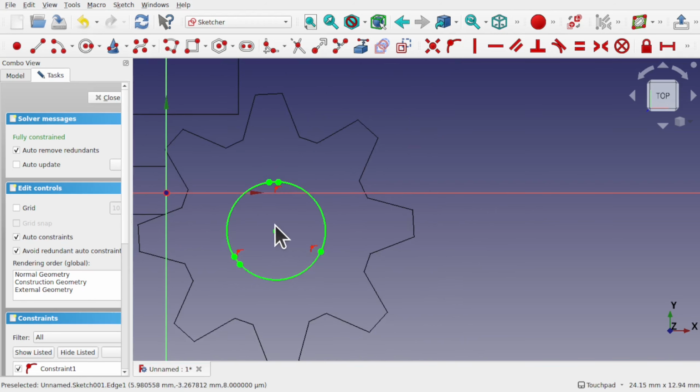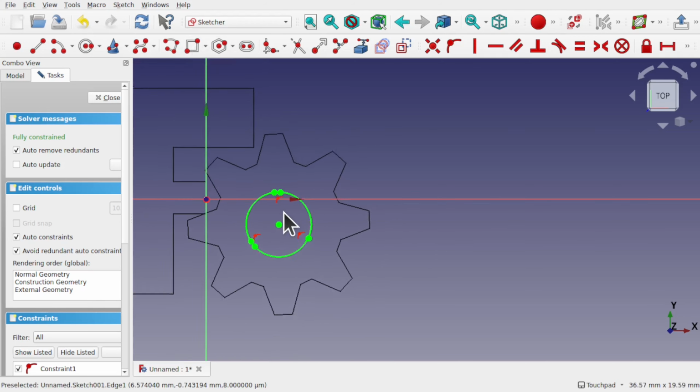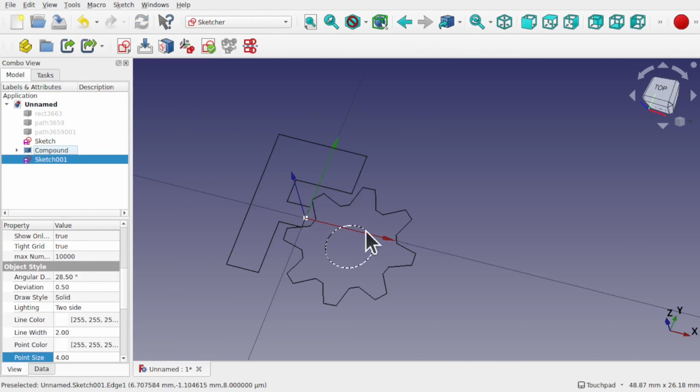If this wasn't a circle, this will become over constrained. We'll have to delete it and think of another way of doing this. We can use any shape, what we want from up the top. Now we've got this sketch. If I close that, you see the sketch sits behind this circle. We can use this to fool FreeCAD in thinking this is part of the geometry for moving this SVG. Well, I say fool FreeCAD, we're just snapping to geometry.